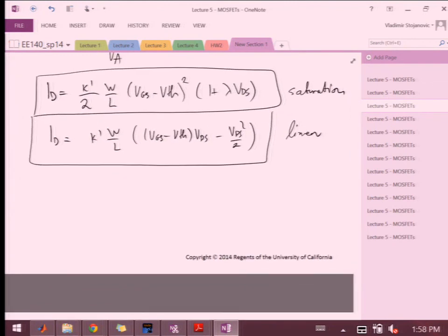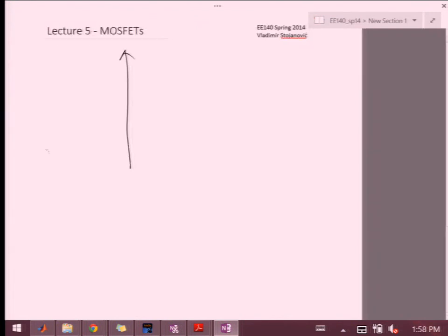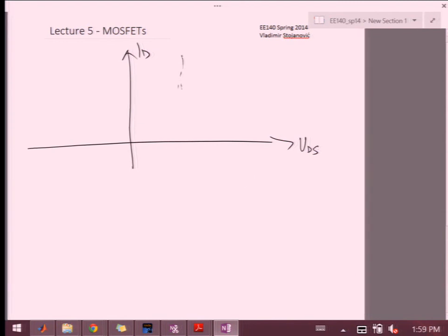So when I now draw the curves to incorporate all of these effects that we talked about, I'm going to draw ID over VDS. The first thing I can draw is the boundary, which is this quadratic. The quadratic says that ID sat equals K prime W over 2L times VDS squared. So I'm going to draw that curve.